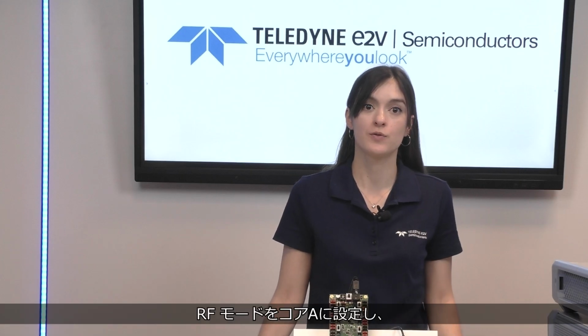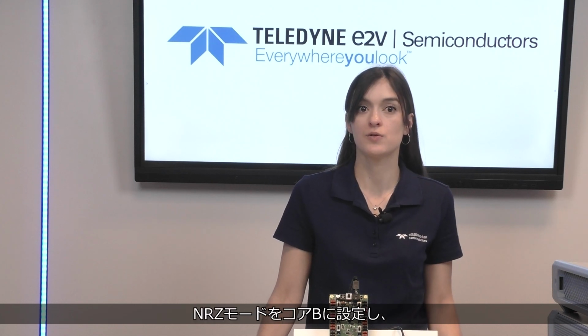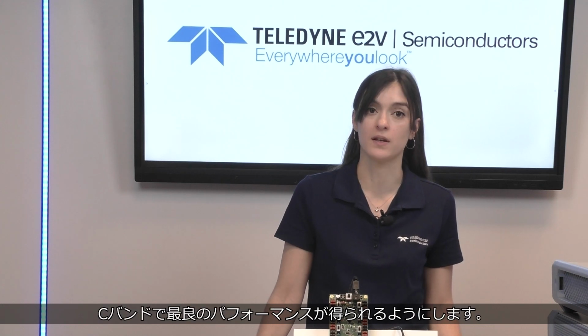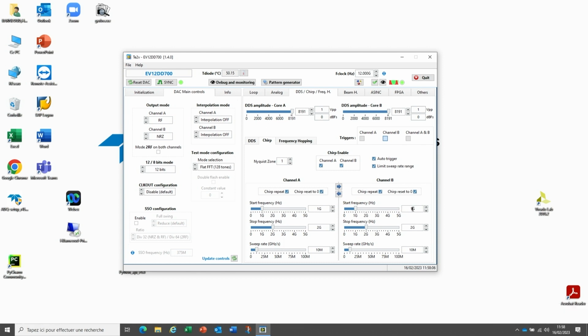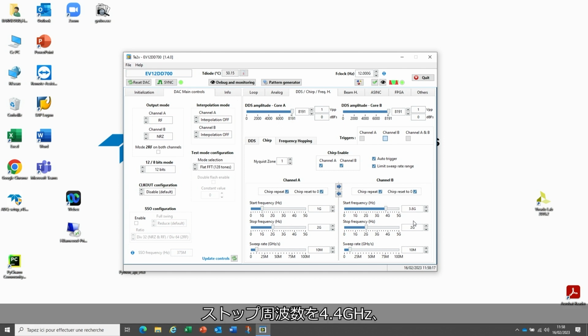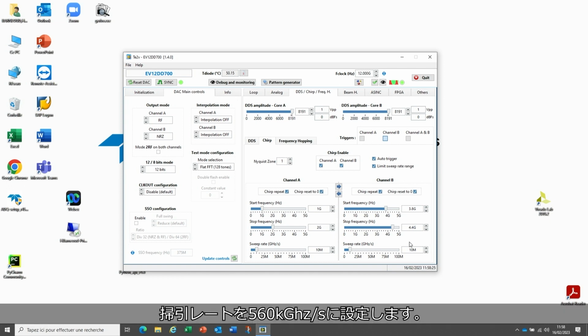Set the RF mode to allow the best performance on X-band on core A. Set the NRZ mode to allow best performance on C-band on core B. Set the start frequency to 3.8 GHz. Set the stop frequency to 4.4 GHz. Set the sweep rate to 560 kHz.